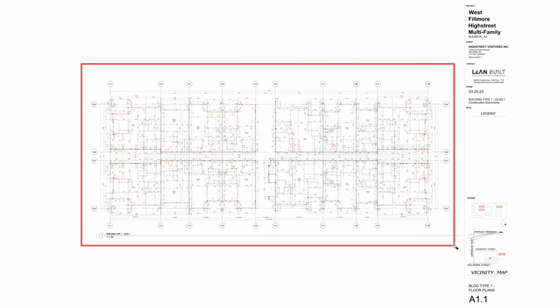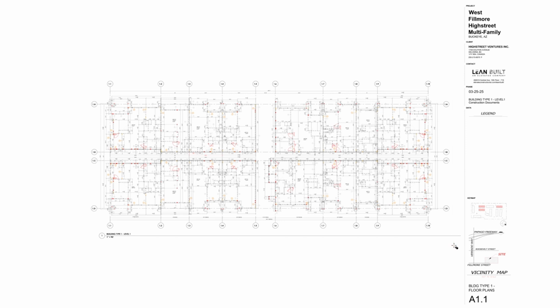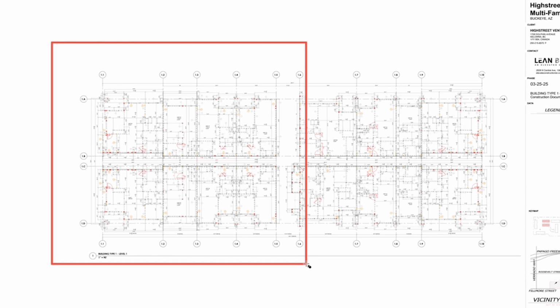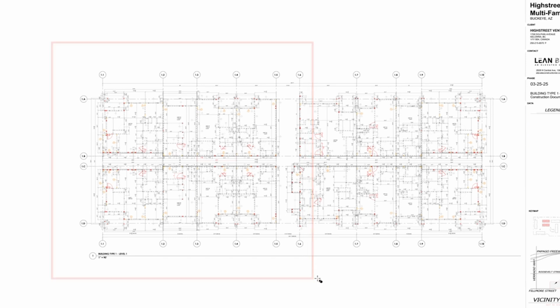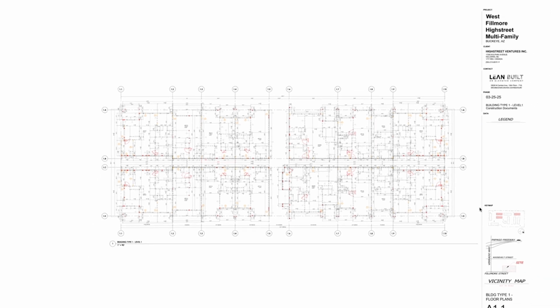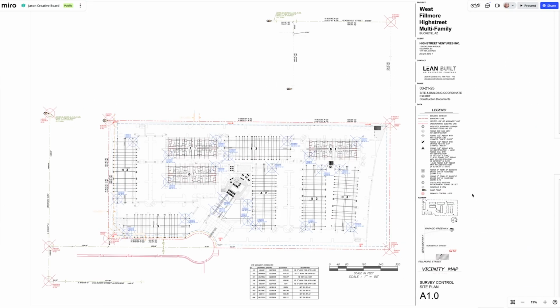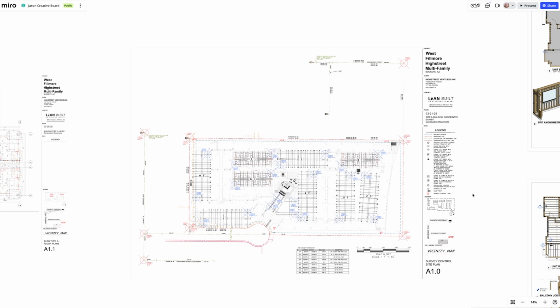And so the reason this is so important is because it's a post-tension slab on grade, and we can't get this wrong, and we can't just go drill and epoxy this stuff later. So this allows us to get out of the ground fast as we start the first placement over here. And so this is a lift drawing that we did, even though it's not a big concrete commercial project, it's just a multifamily building. Let me give you another example of a lift drawing that you would do for any type of project. So we have 9 buildings on our project, and it's quite a big site actually.